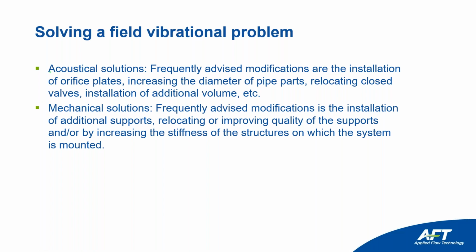Most frequently advised acoustical solution modifications are installation of orifice plates, increasing the diameter of the pipe or the ports, relocating closed valves, or installing additional volumes. That is the most frequent acoustical solution. Regarding mechanical solutions,